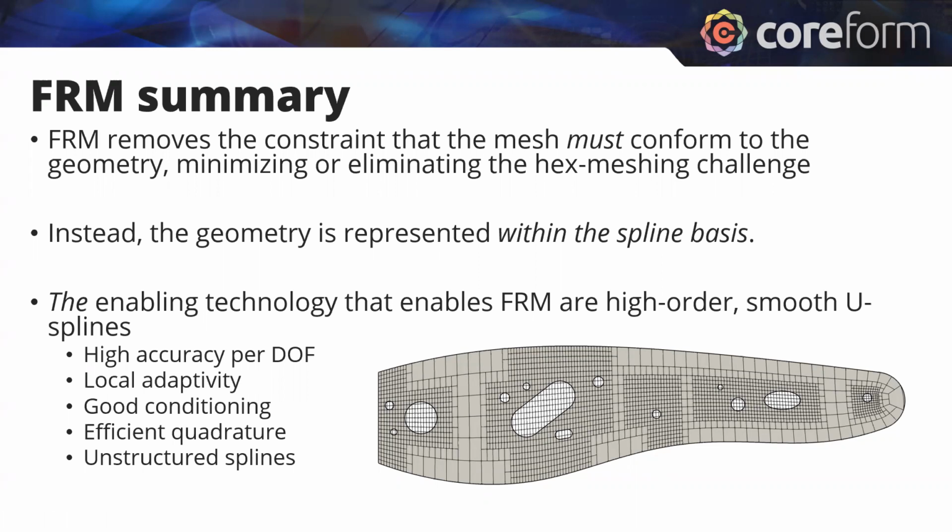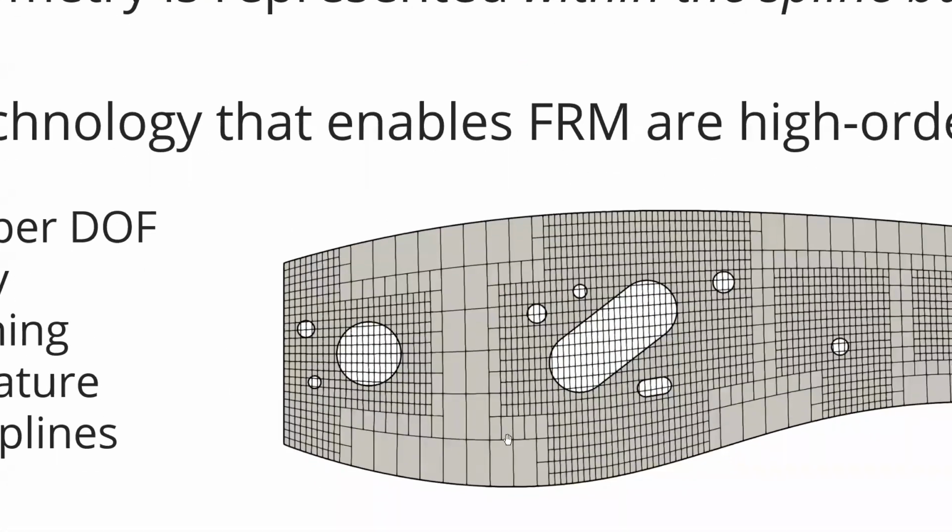Yeah, so hanging nodes is kind of the colloquialism for a node that's here at this T-junction. But the difference is that a hanging node essentially means it's not supported in the basis, and so you might have to use a tie constraint between them. And that tie constraint might happen automatically, or it might be something that you as a user would specify in your prep.